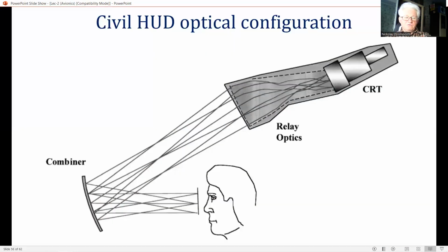The optical configuration of the HUD is shown in this figure. The thin spherical combiner incorporates a rugged dielectric coating referred to earlier. These highly efficient selective wavelength coatings are very hard and are not affected by the atmosphere, and permit a relatively thin combiner to be used, rather than the thick sandwich necessary with combiners employing a gelatin-based hologram.